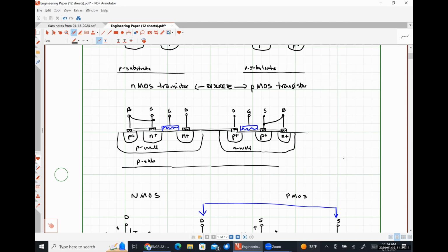It is there to make sure, so we're depositing metal here, and then we have a lightly doped semiconductor. We put this highly doped semiconductor so that there's a transition from highly conductive semiconductor to lightly conductive semiconductor, so that this is an ohmic junction effectively, and this is also an ohmic metal semiconductor junction. If we tried to put metal directly on the lightly doped substrate, we wind up with a rectifying contact, which is not what we want. We don't want a diode anywhere in this thing. This is a field effect transistor, not a junction transistor.